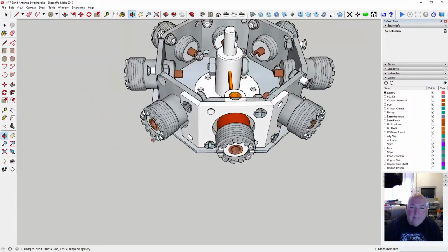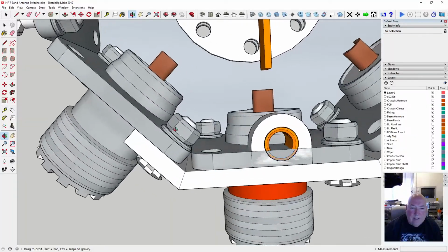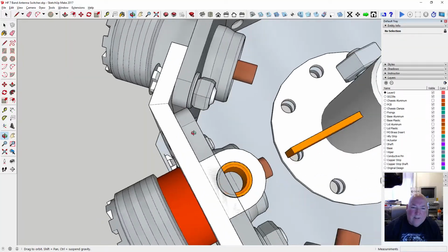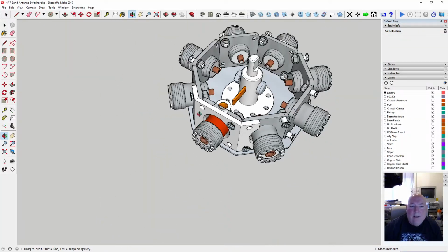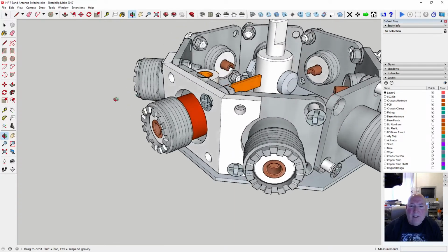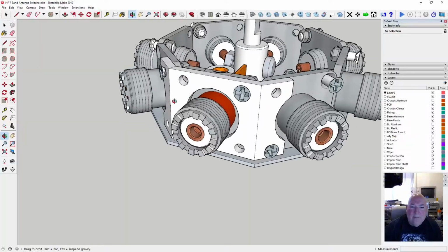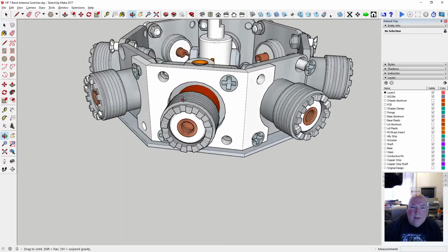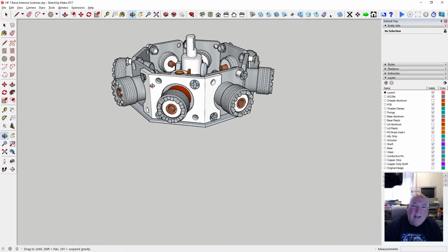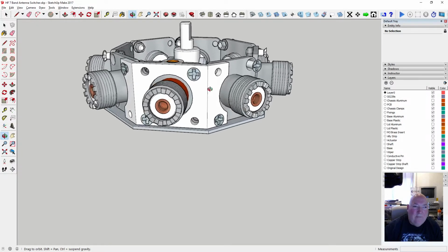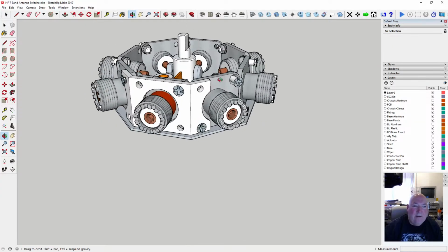That's okay. You can see that nut now no longer gets in the way of this fixing, so we've got two fixings. So we've reduced the number of fixings by 2, divided by 2. Yeah, it's going to have a little bit of RF leakage there, but as long as the main screen is there, it's a bit like a copper plane on a PCB. It's not fully there, but it still acts as a Faraday cage.